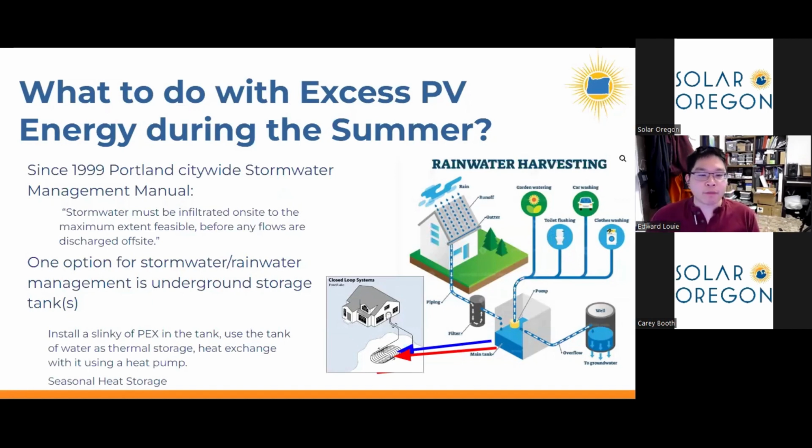In Portland and a lot of wetter climates, if you do new construction, they require you to have a plan to handle and manage the on-site stormwater or rainwater. Oftentimes this is done with gutters that run into kick out deflectors, and you're essentially pouring the rainwater from your roof onto your lawn, or you have dry wells on your property to manage that rainwater.